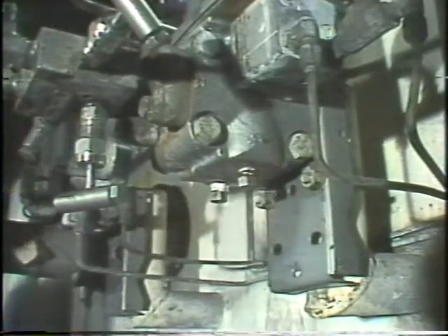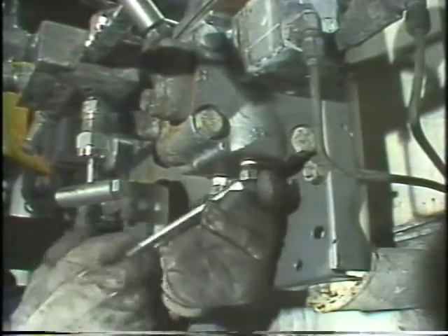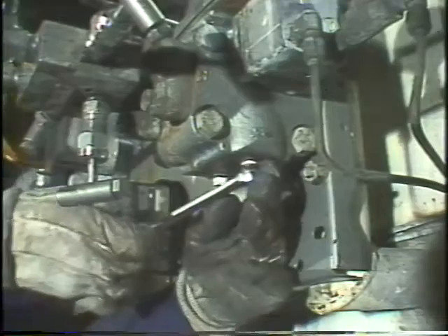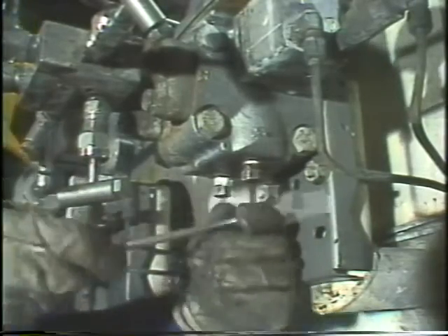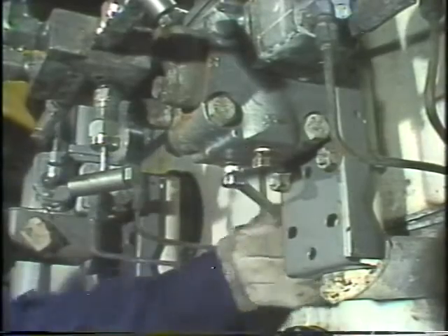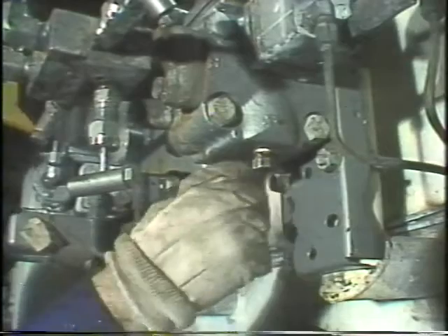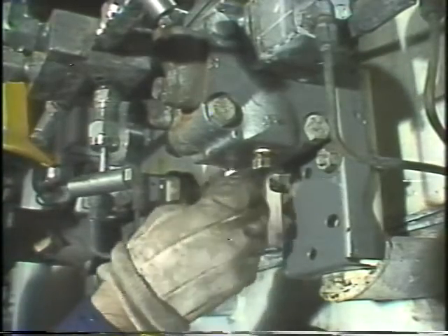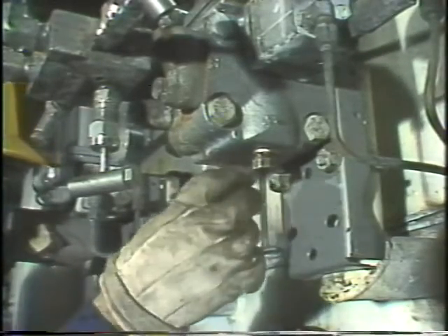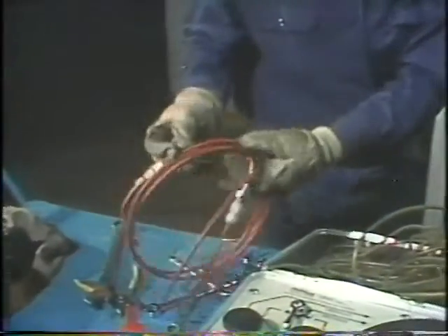By removing the connections that come from the process to the transmitter, that prevents a vacuum being created inside the DP cell body and holding any water in there. That makes sure I get all the water out of the DP cell so my readings will be accurate. Take care of this low side plug. There, that ought to do it.